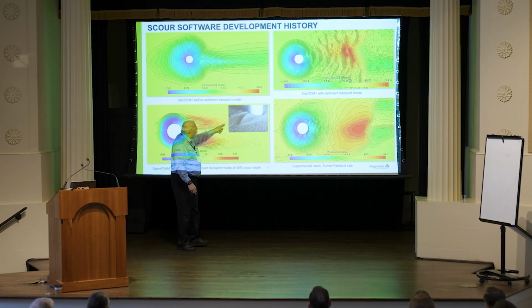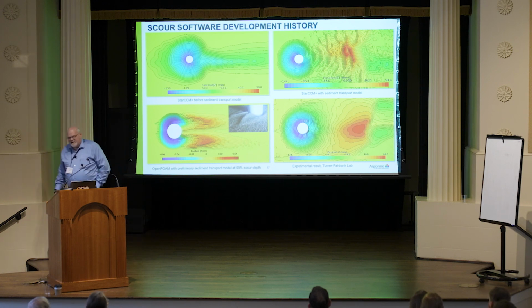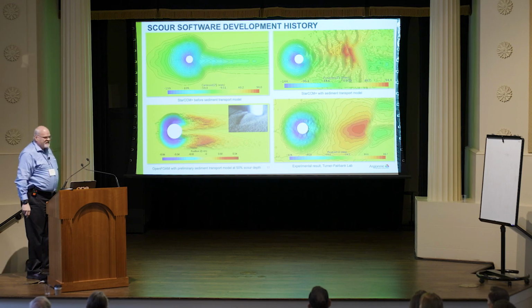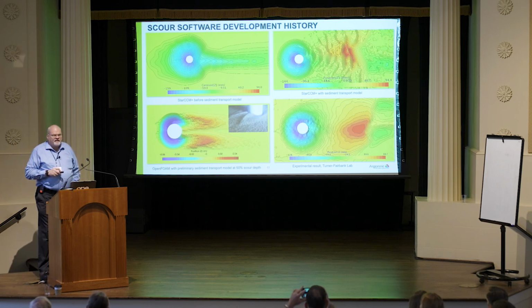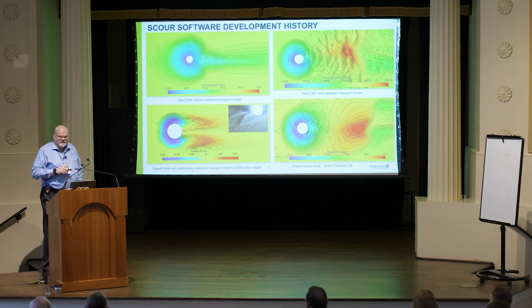And then we had an experiment that Cornell did for us that took a video camera underwater to show what the erosion patterns look like, right? And I don't want to overpromise, right? But what I get out of this kind of calculation looks somewhat similar, right? That's very promising, at least in the early stages, right? So it shows that the physical phenomena are probably correctly caught at this point, but it's completely uncalibrated, right? So I'm running this without tweaking any numbers. It's the exact Van Rijn formulation and so on. Because when you develop this kind of thing, you don't want to put any kind of smudge factors in there. I'd rather explain why things look different.